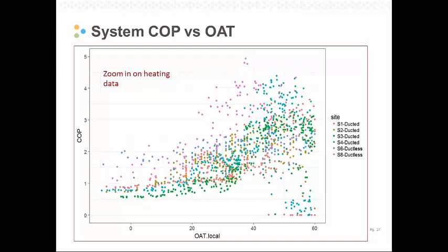But if we look at the heating performance down below 0, you can see that for the ductless systems, those daily system efficiencies are a little bit below 1, where we're running both the backup furnace as well as the heat pump, as we get a little bit warmer out. But the ducted systems, the blue and pink, have efficiencies that are greater than 1, and that's because that heat pump is still running all the way until negative 13 degrees. And so we're still seeing COPs that are higher than 1, which is pretty great.